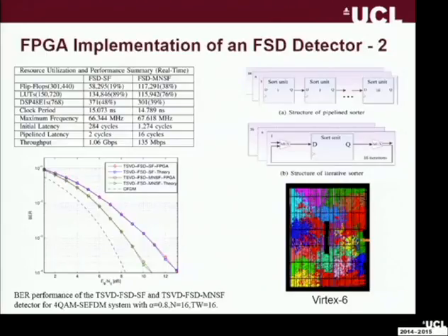Right, okay, so within an FPGA, for those of you that know more about digital electronics, you've either got a fully parallel architecture, which means that on each clock cycle you carry out the entire algorithm, or you've got a fully pipelined architecture, which means that you minimize the area but you increase the latency, or you've got something in between. And this is what we've got here, a semi-parallel architecture.